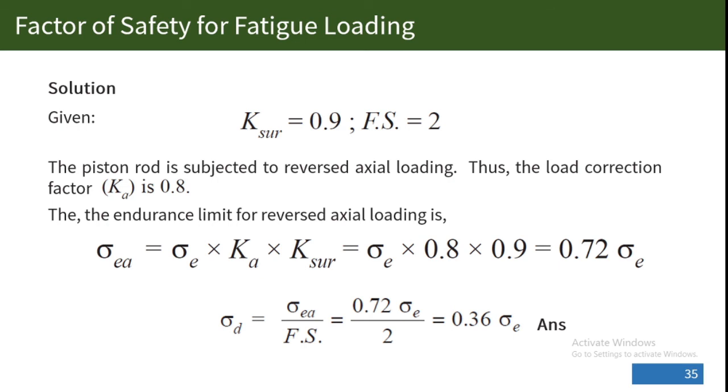I also discussed fatigue and the time stress diagrams. With time stress diagrams, we determined the relations between stresses, for example, the relations for mean or average stress, reversed stress, repeated loading, the stress ratio R, and the relation between endurance limit and the stress ratio.